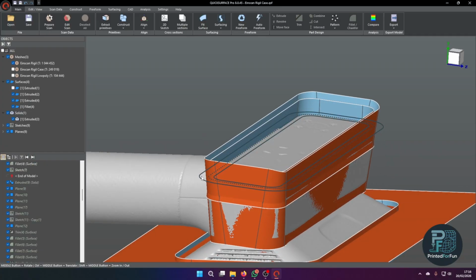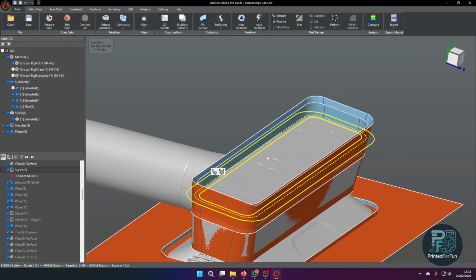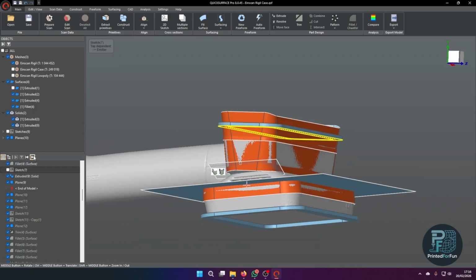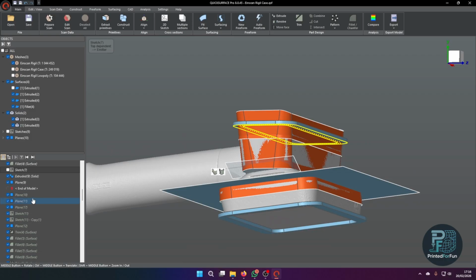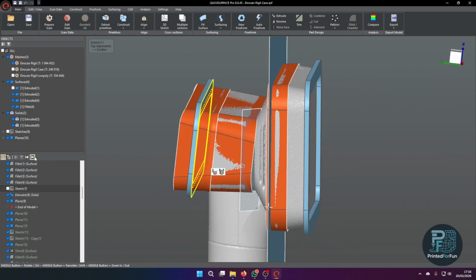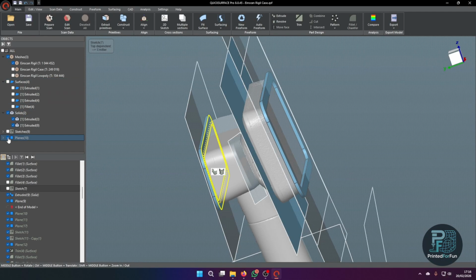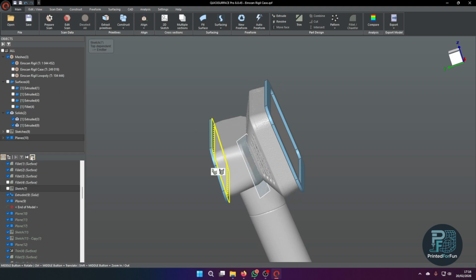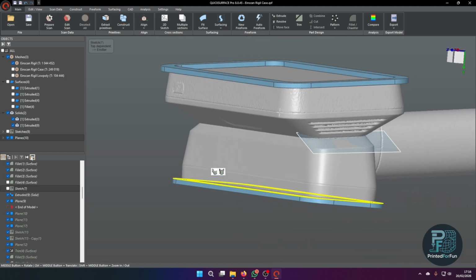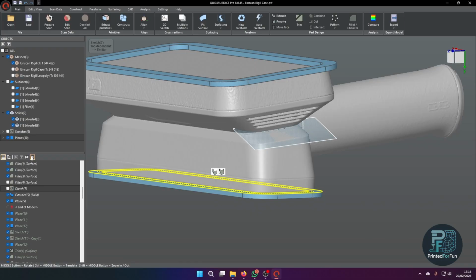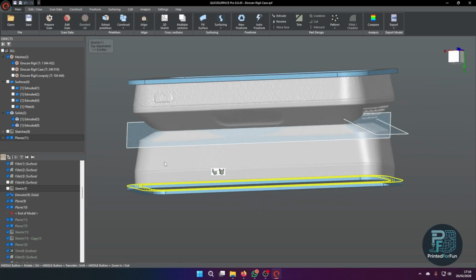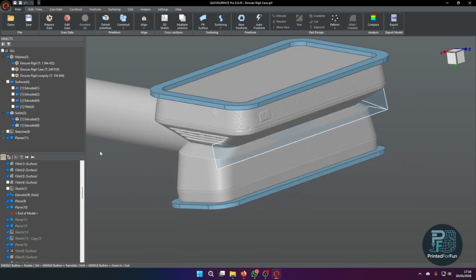But now let's again create the protection lip for the emitters in front with again a sketch and 2 offsets to the sides. I extrude it, and now I can fit planes directly on the top. So let's hide the surface now a bit, the planes, so we can see them better. Here I was a bit lazy, I didn't want to create additional sketches, so I just directly fit surfaces by selecting a bit of the point cloud that the plane will lay on, and then fitting a plane through it.